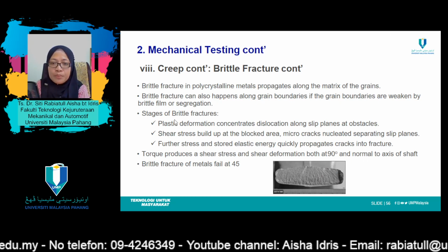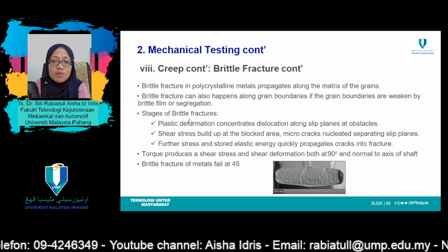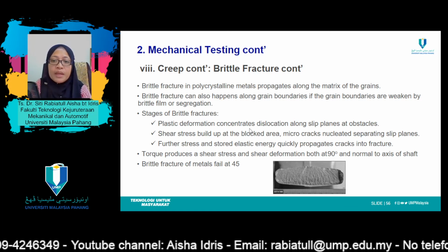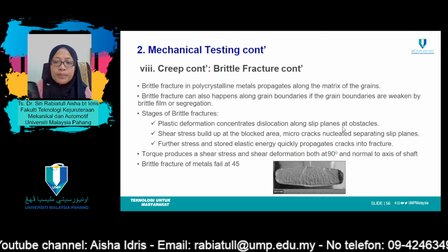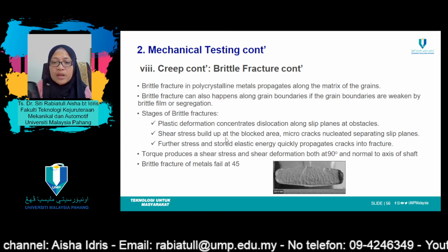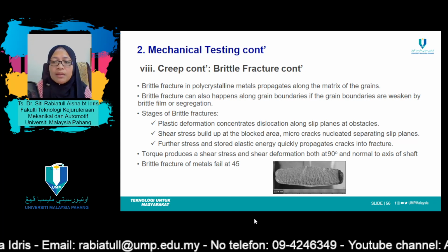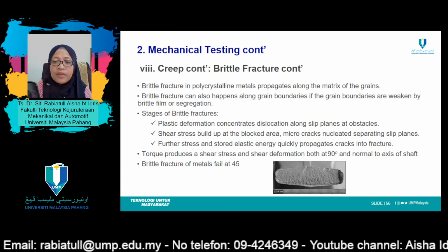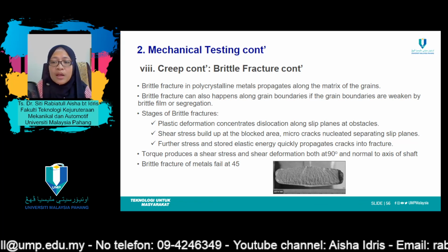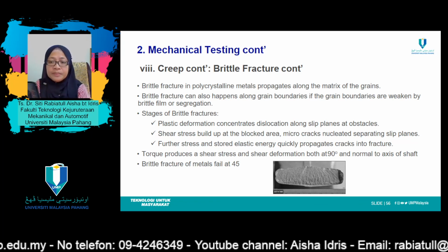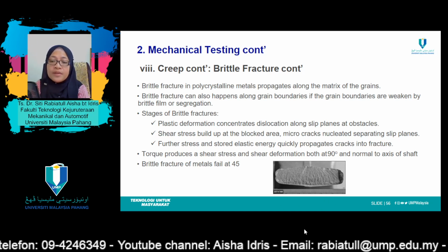So in brittle fractures, the stages include number 1, plastic deformation concentrates dislocations along slip planes at obstacles, and shear stress builds up at the blocked area. Microcracks nucleate, separating slip planes, and further stress stored as elastic energy quickly propagates cracks into fracture. And finally, producing this type of surface topography.